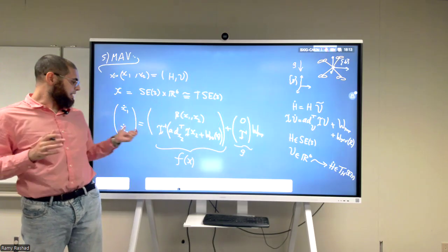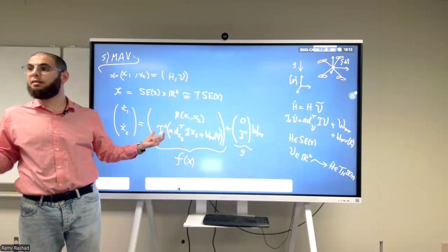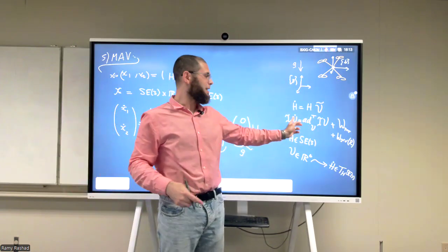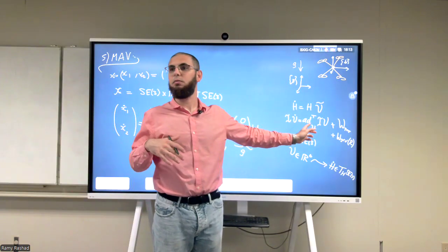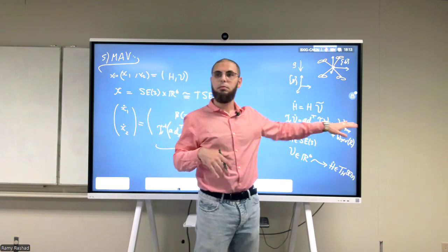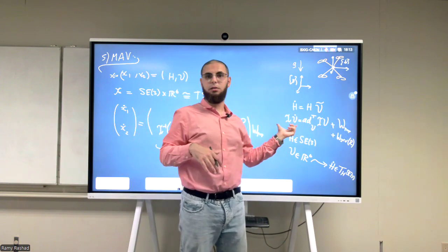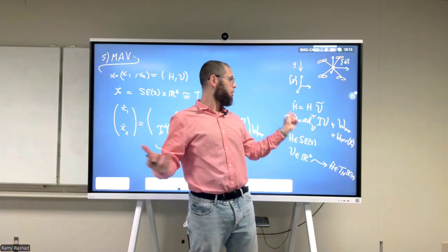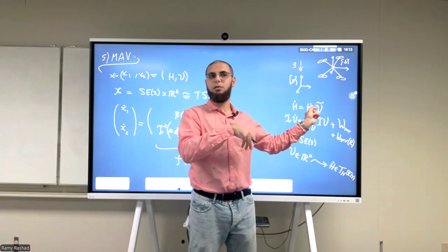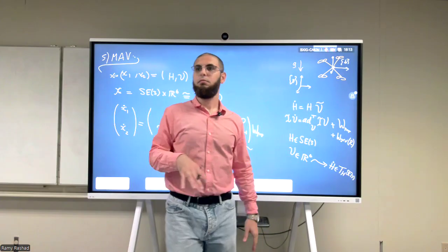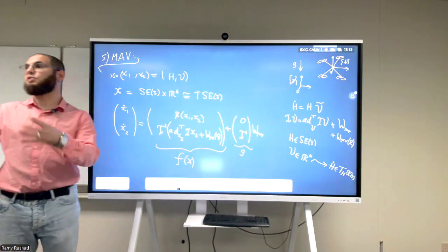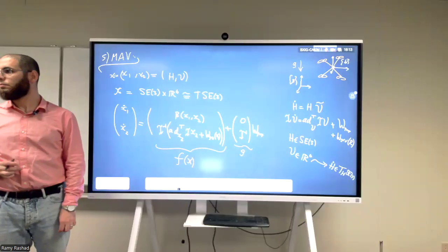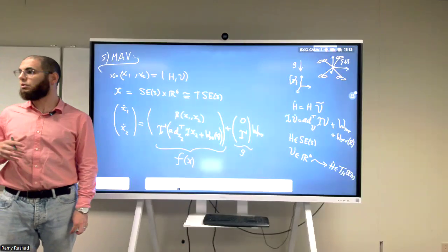In this case, the satellite equation, the second equation, which was related to the momentum or the evolution of the twist, is depending on itself. It's not depending on the h, right? So I can solve this differential equation. If you're integrating this, you solve this one, you take the v, you plug it in here, you integrate it, and you get the h separately. This is what it means, right? You have some sort of structure. For the gravity, we represented it with the wrench, right? Yes, it's a gravity wrench.